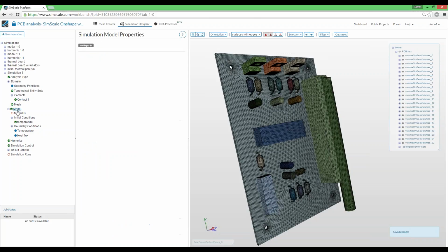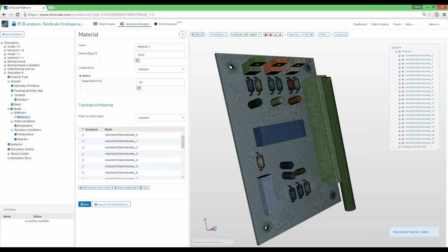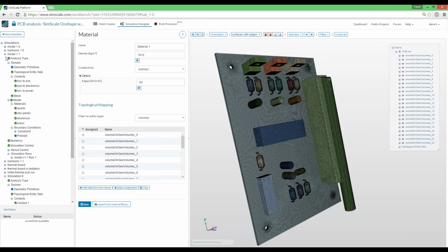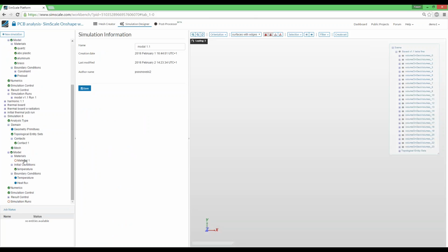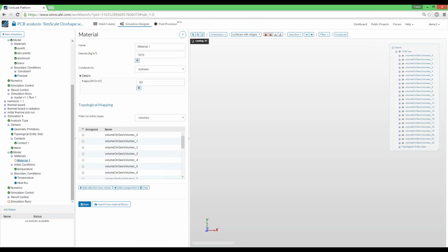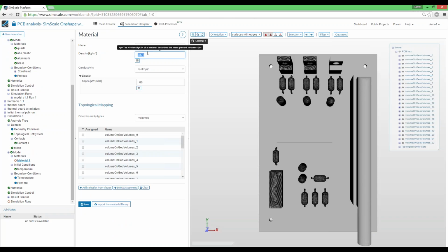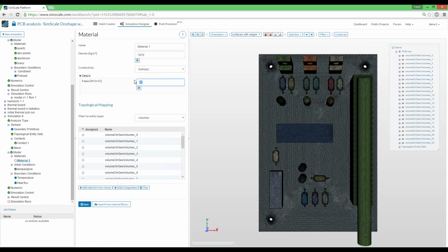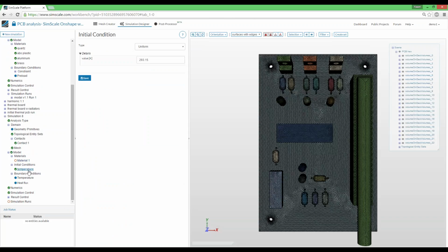All right. Further, we go down with our settings, nothing to do in the model, but we need to add materials. The way to define them is exactly the same way as we did for the modal analysis. So we just have a similar approach, even though we are using a different solver. We need to provide the density and the heat conduction coefficient. Obviously, this would take some time, so I'll just skip that, and later we'll see the predefined simulation.